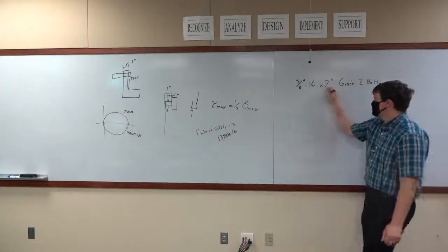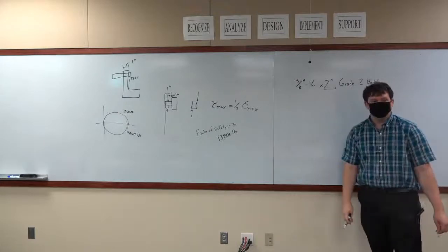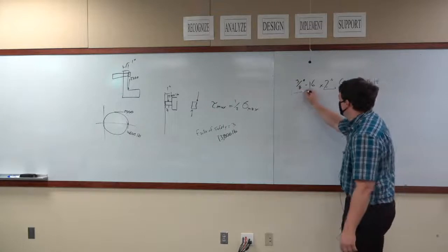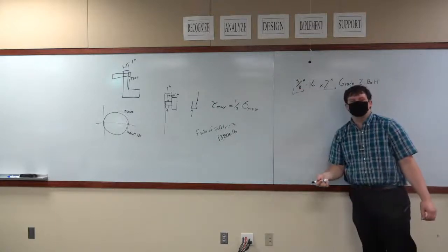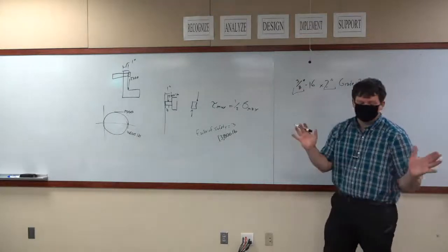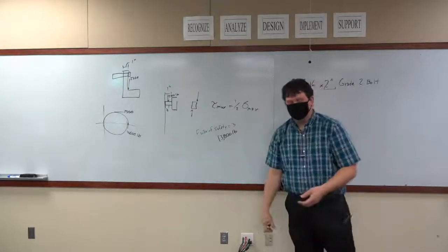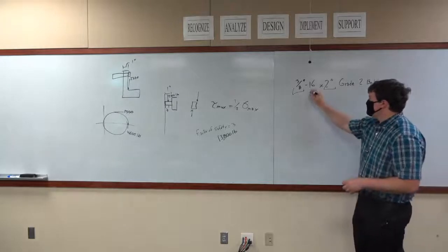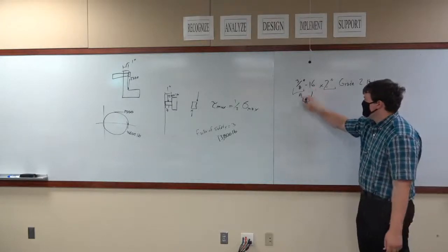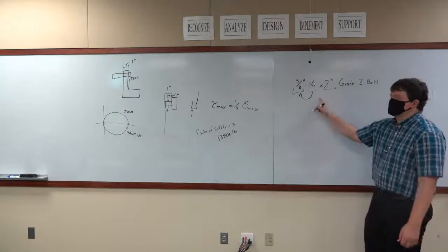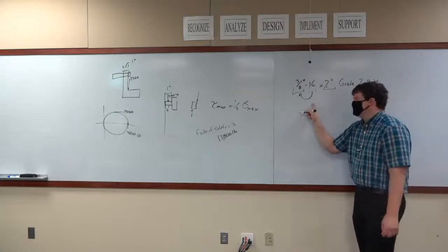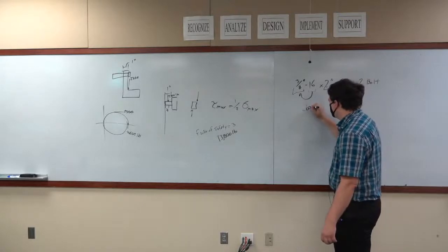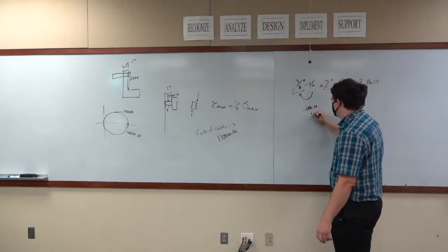Okay, this number has to be greater than 1. Hopefully everybody picked a number greater than 1. This number should be greater than 1/4 of an inch. Some of you picked 1/4 of an inch, which is fine. We didn't explain it, but generally this is what I would do. And this number here depends on this number, because this is the number of threads that happen per inch. 16 threads per inch is considered coarse threading. Coarse. I think it's 16.